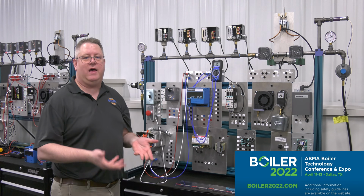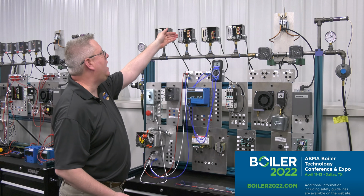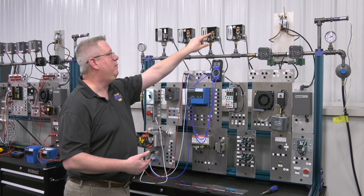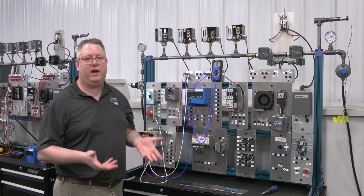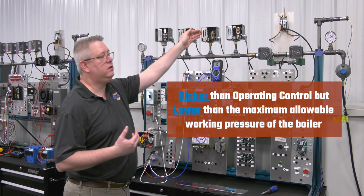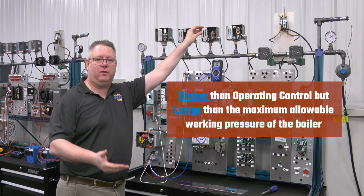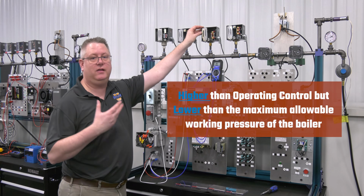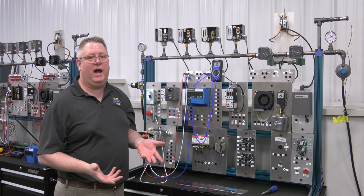But where do we want to set that? If we've got our operator set to shut the boiler off at 100 psi, we obviously want this set higher, because if we have to come out and manually reset this in order for the boiler to cycle every time, well, that's just not very practical. So we want it higher than the operating control, but we want it lower than the maximum allowable working pressure of the boiler, because we want it to shut the boiler down, preferably before we lift the relief valves on the boiler, because if they lift, they may or may not reseat, and that's a whole other ball of wax.